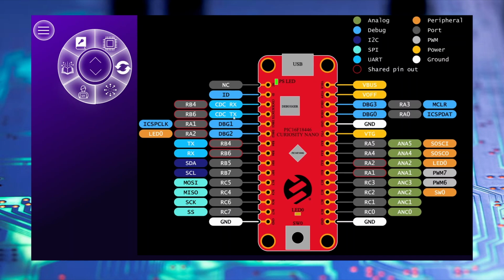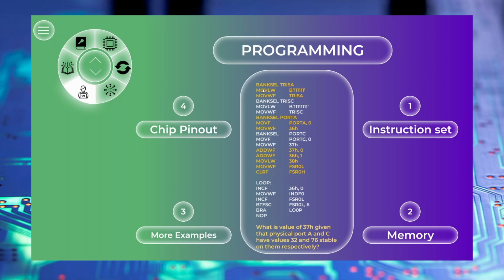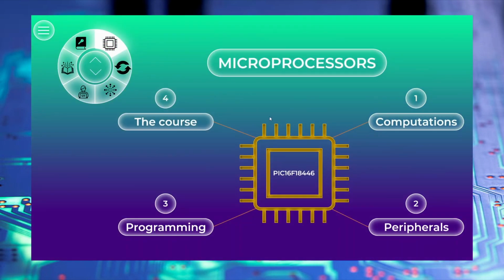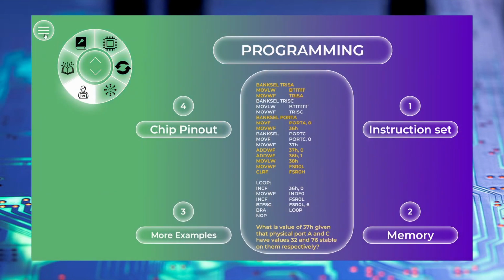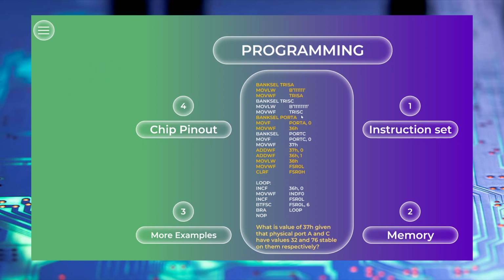So it's very important to know all these pins, because each pin here has a corresponding bit, and each port has a corresponding register. For example, here you can see we are saying port A. So a port is just a collection of physical pins, right? If you look at the chip itself, you will see that it will have these pins. These are the physical pins.